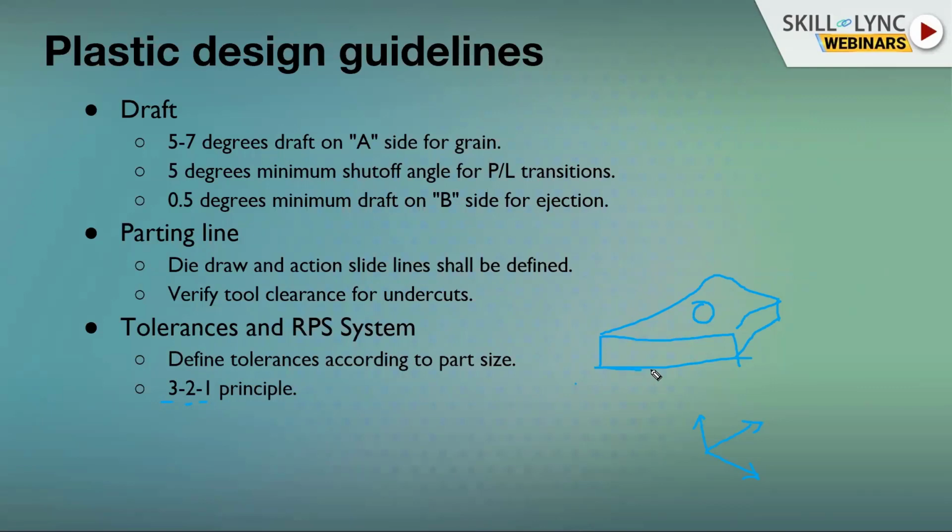Now when I fix the plane, so when I rest this part on the plane here, let's assume this is a plane. Now when I rest this part on this particular plane, then 3 degrees of freedom will be arrested. Like this translation up and down because it's resting, right? And then it cannot rotate along Y direction. If I assume this as Y, it cannot rotate. So this is 1 degree of freedom fixed, 2 degrees of freedom fixed, and also it cannot rotate along X direction. So there are 3 degrees of freedom fixed.